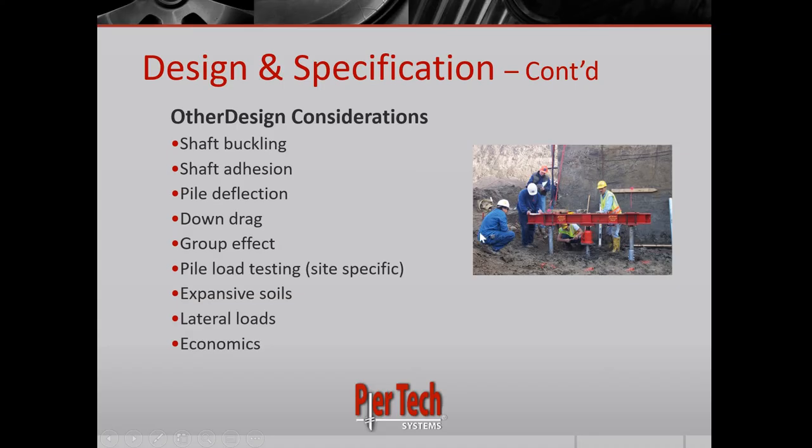If a pile is within that soil, it's acting like a column, and it's not braced laterally from buckling. So buckling can become a concern. Anytime you see that in a soil report, or your torque values are essentially nothing as you're going into the ground, you may have buckling concerns for that pile. It's very important to get a geotech investigation and get a structural engineer involved in those types of soils. The solution to that problem would be increasing the pile diameter or potentially casing around the pile after installation. Both of these are acceptable methods to prevent buckling.